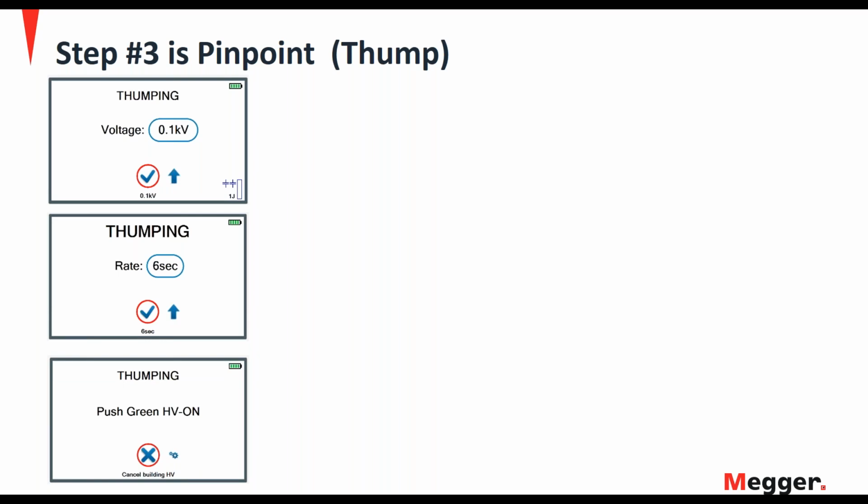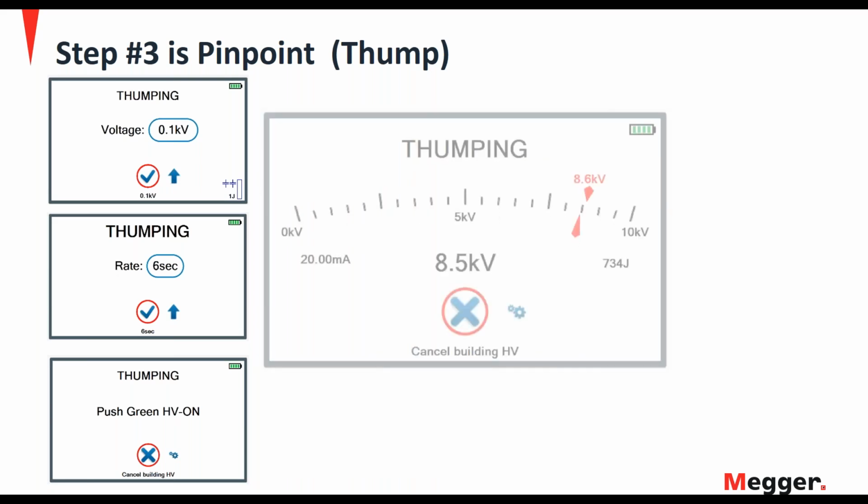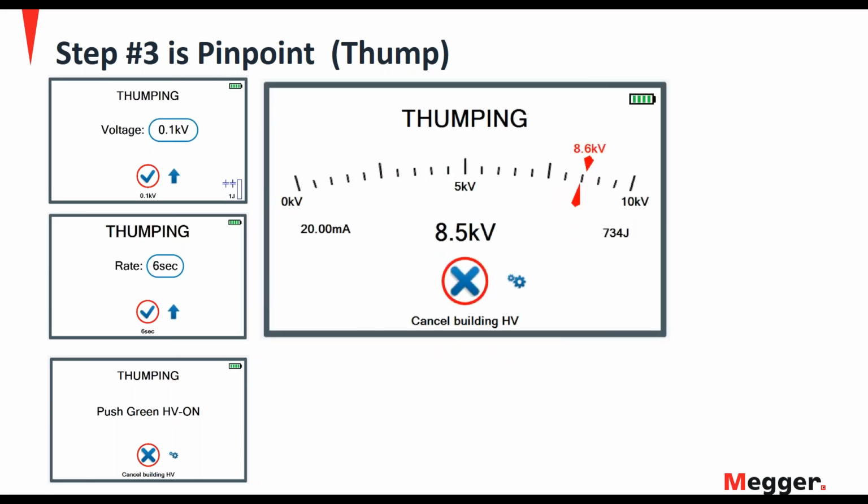I should pause here and mention one of the nice safety features of the Smart Thump 25 is it's always asking permission before it goes hot, so that you're not going to be applying voltage except for when you choose to. And then at this point we would be thumping.